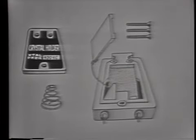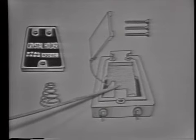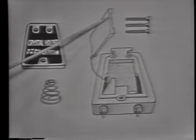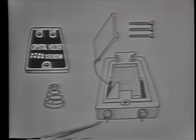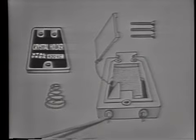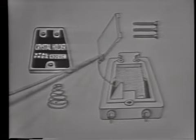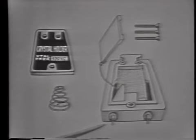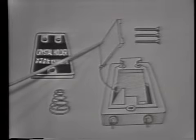The crystal will be placed in the holder between two parallel plates. The plates have an air gap between them, which allows room for the crystal to vibrate. The two plates then are connected to the pins. Now these are the pins that will allow the voltage to be applied to the plates. And also the pins will allow the crystal to be connected into a circuit in much the same manner as a vacuum tube. The spring will keep a constant pressure on the plates and hold them firmly in place.